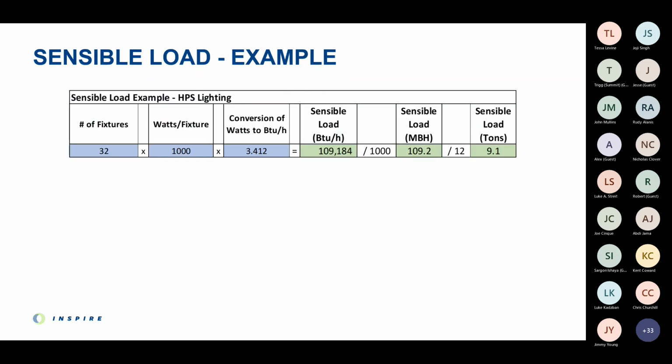Sensible loads include anything that generates heat we can feel within a grow room. Horticultural lighting fixtures account for 95% or more of the sensible load in indoor plant environments. Any other appliance within the space that uses electricity will also add to the sensible load, such as fans or irrigation pumps. Many rooms also have standalone dehumidifiers hung within the space, which generate a lot of waste heat while dehumidifying the air.